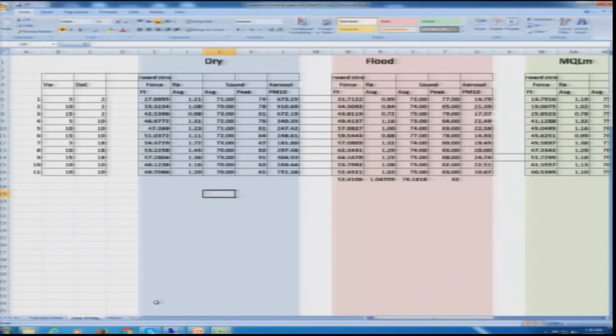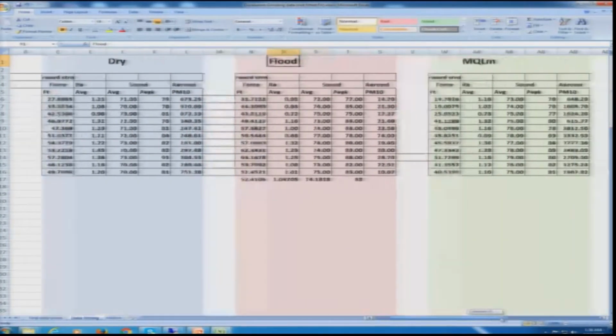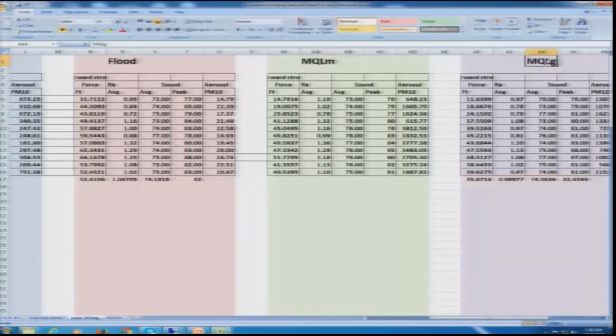So, in case of grinding, this was the input data. So, these are all treatments. Full factorial design was chosen. Full factorial means all the experiments were conducted. All the possible combinations are used as treatments, and the experiments are conducted accordingly. So, this is the data for dry machining, data for flood machining, for MQL machining, and for MQL machining using a green fluid. This green fluid here is my vegetable oil. This fluid here is from M, it means mineral oil here.